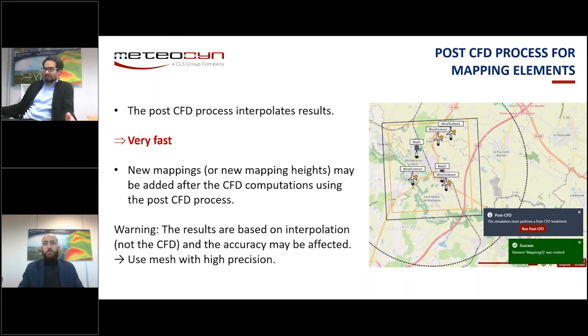Or for new mappings at different heights, so this is fine. However, be careful, don't use this functionality if you place new mapping outside of the mappings. This is not a good idea because the results will be based on interpolation only and not the CFD, so the accuracy may be affected. So yeah, keep this in mind.